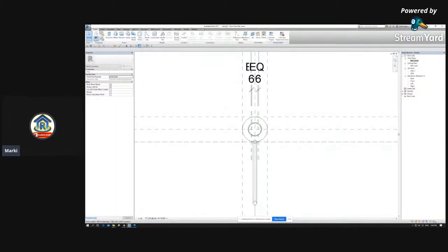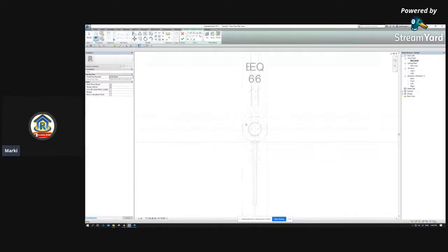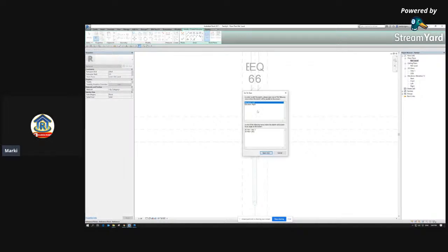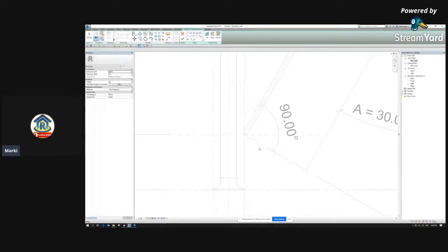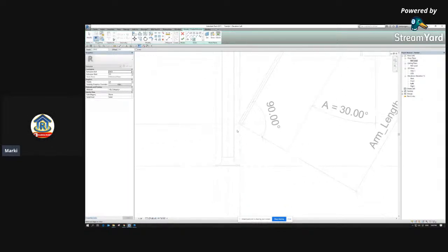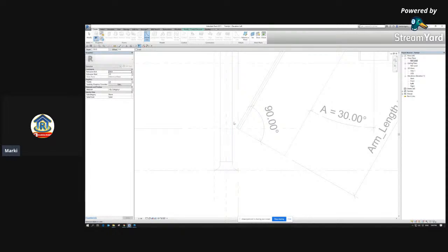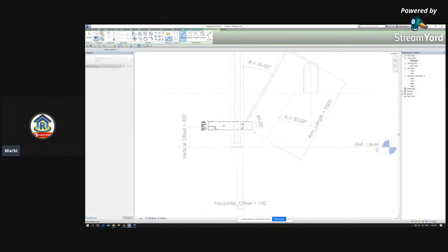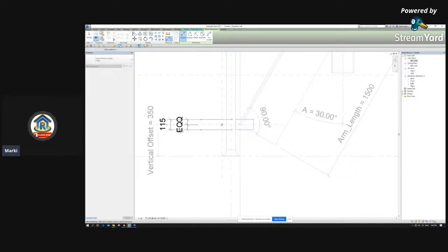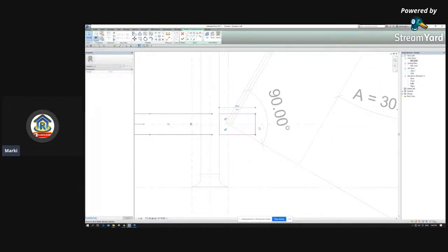Okay, once it's done, we can create an extrusion, set the work plane, pick a plane, set this one as a reference, and then go to my left hand side. From here I can sketch it out. I can sketch a rectangle here. Then I can make this one equal and put a parameter. You can put a parameter if you want to, or you can simply leave it like that, or lock it. Yep. And then this one I can fillet arc.